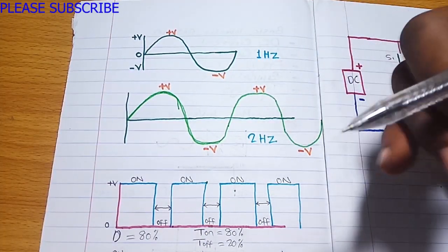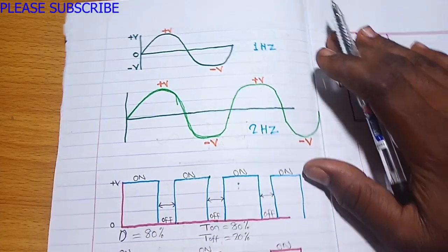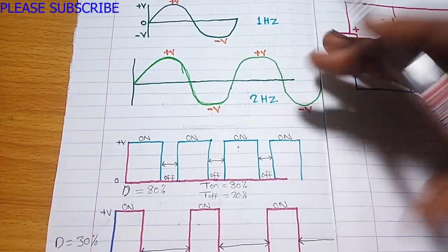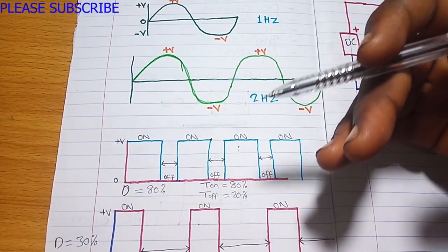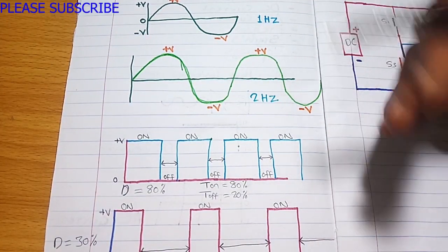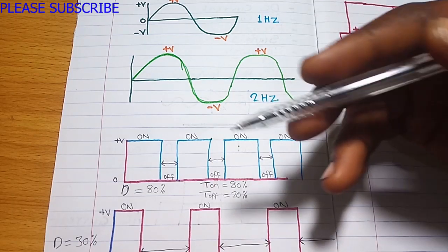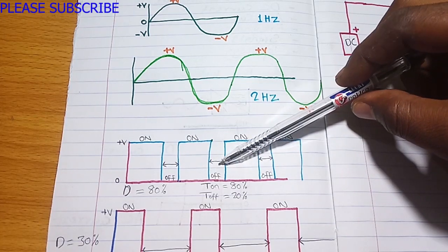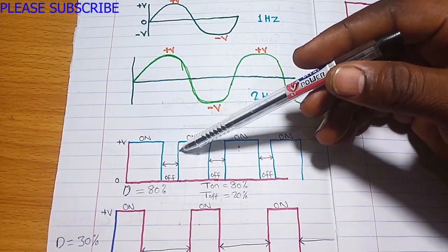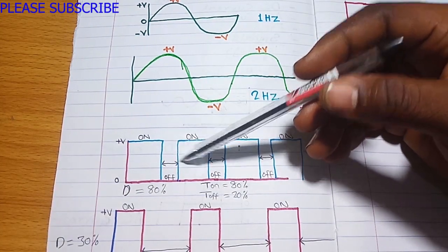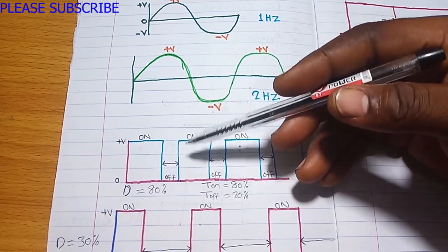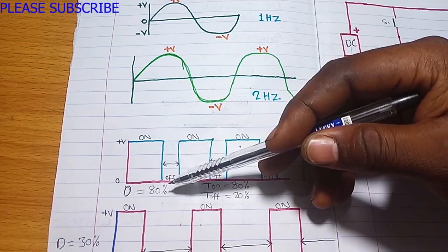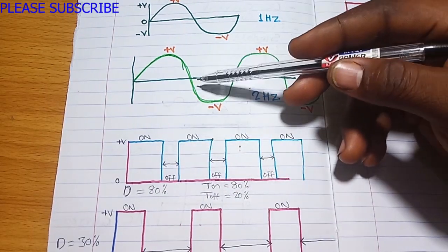And then let's talk about the duty cycle. I'm just trying to explain it. We have not gone in depth on how an inverter works. I'm just explaining the basics of AC, DC, and frequency, and the important role they play in an inverter. This is what we say about the duty cycle. The duty cycle simply means the percentage of the on time versus the off time. Just like the way I drew this signal, I'm using a square wave, but this is applicable to any wave.